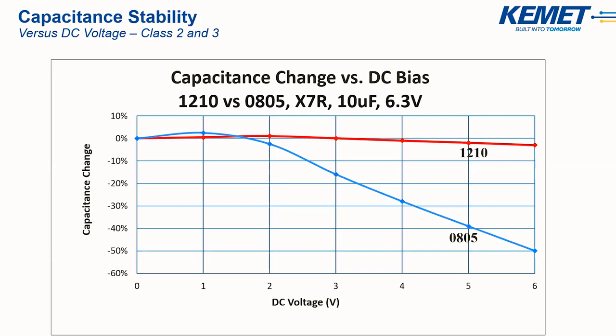So if you're considering going from a large case size to a small case size and you're downsizing, you have to consider the VCC effect and what it's going to do to the performance of the MLCC.